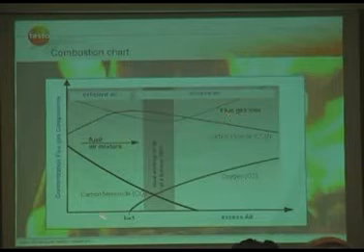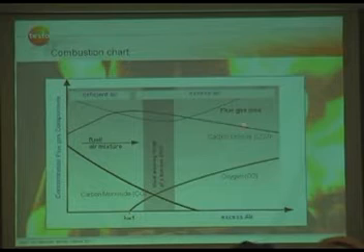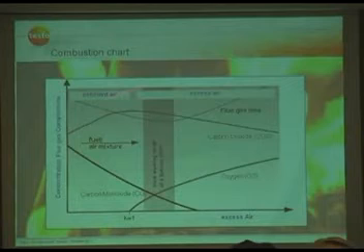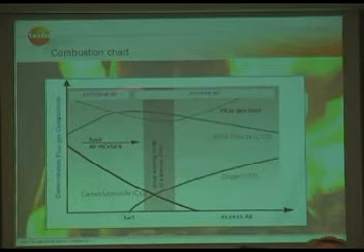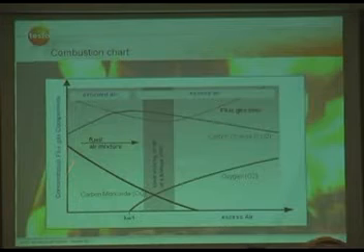And to get a feeling with regard to lambda or excess air, it's required to measure CO2, oxygen, and CO. According to those parameters, you can adjust your burner, boiler, engine, whatever, to your lambda value. Basically, every fuel, if it's solid fuel or liquid fuel, has its own chart with the CO2 max value, and then according to this fuel, you can adjust your burner for the highest efficiency.